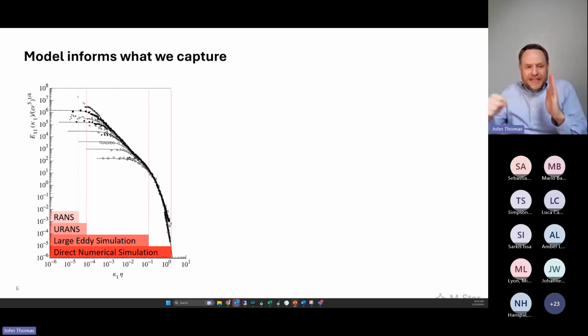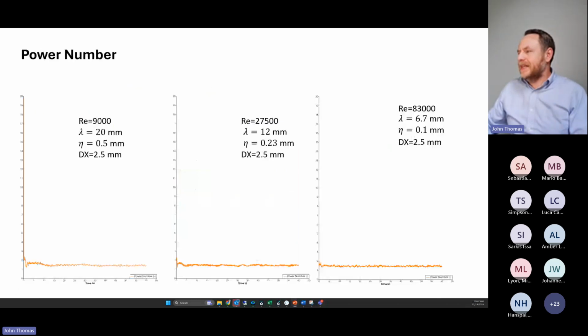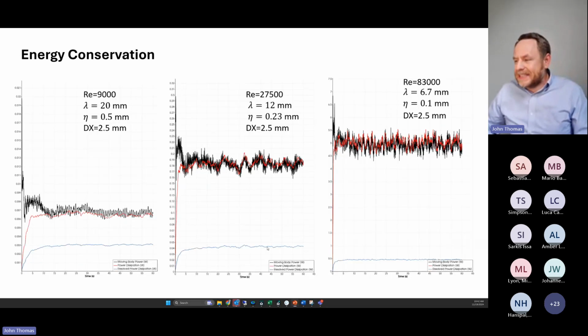And so here I'm shifting not the resolution, but the Reynolds number under the feet of the LES filter and watching it respond. Sorry to be jumping around, but it's kind of cool. And so again, from a macroscopic standpoint, from a power number, total EDR, local EDR, it's all good. What this is telling me is that at some of these higher powered voxels near the impeller, the subgrid model is doing its job and doing it well, in the sense that it's correctly capturing the total EDR, despite the fact that I'm only explicitly resolving, in this case, less than 10%, right?